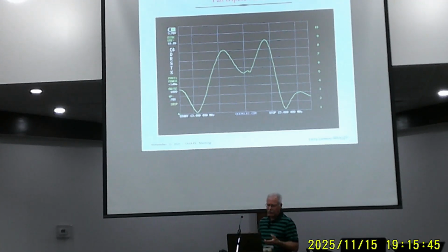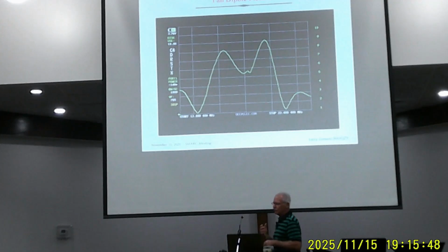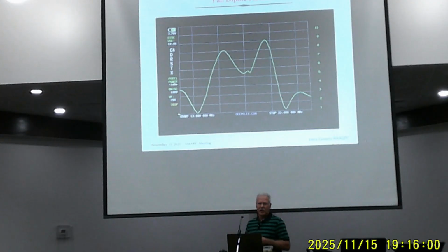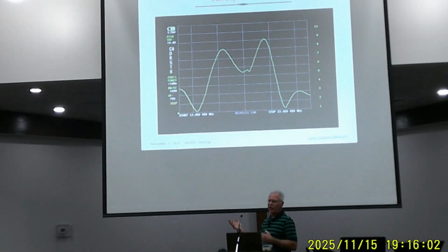The port 1 power, that plus 1 dBm, he has 4 settings of how much power this will put out. -10, -4, -1, and plus 1 dBm. That's kind of a set it and forget it thing. You really don't have to go through that every time. For antenna stuff, I usually set it to the highest power, just figuring that'll be less noise that can get in there when I'm actually testing the antenna. So I generally never change that.